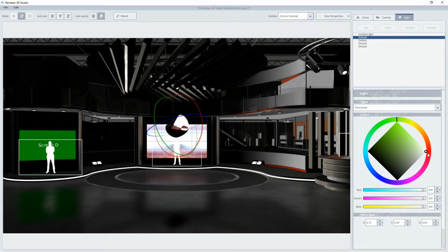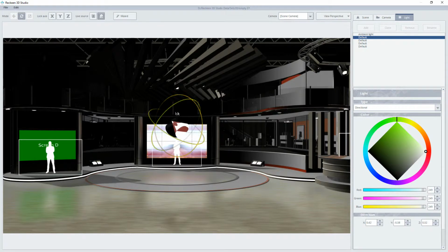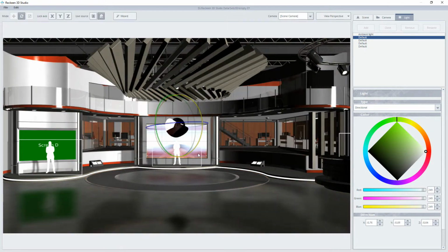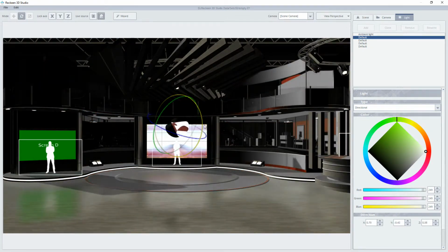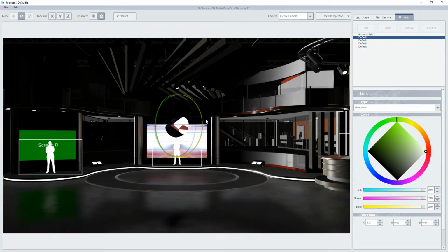The second default type of light is a directional light. Such light falls from a specific direction, not from a specific position. Even though this object is by default located at the point x0, y3, z0, it doesn't mean this is a physical position of this light. We can imagine that this is a certain infinite plane, which rays fall in parallel with a specific direction on all the objects, like the light of the sun.